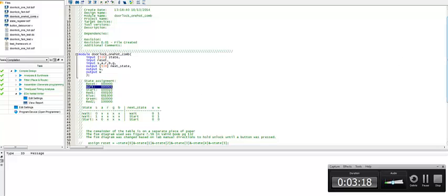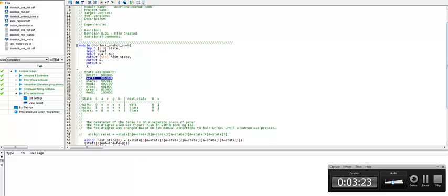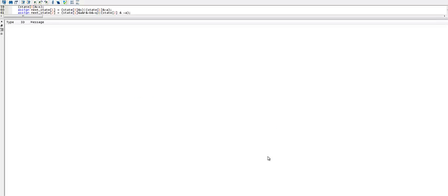Taking a look at some of the equations, again, I don't have to make a state table, but I have some equations here that I could show you. So let me set those up. Without giving everything away, because I want you to have to do some thinking in this lab, here I have next state 1, which is basically the start state. How do I get there? I get there if I'm in state 0, which happens to be the wait state, and S is equal to 1. And then how do I stay there?